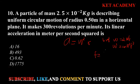We're simply going to change that to per second, which will be 300 revolutions per minute. We know that 60 seconds makes 1 minute, so this will give us 5 revolutions per second, that's our frequency. So substituting in our formula, we're going to have the linear acceleration to be omega, which will be 2 pi. The 2 there will become 4 since we are squaring. Pi squared, and now it will be 5 squared.